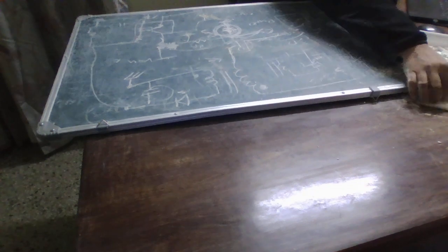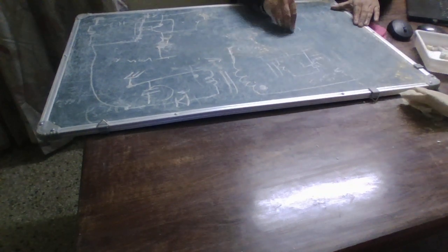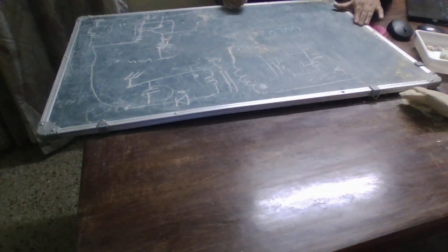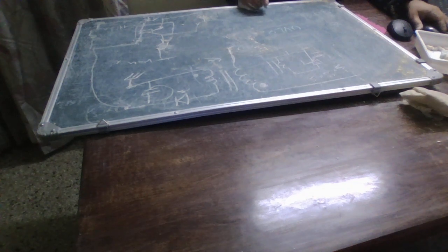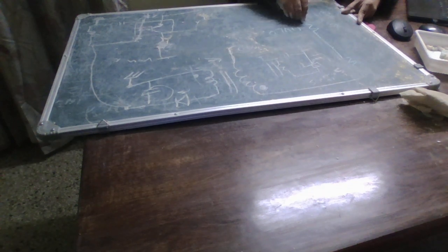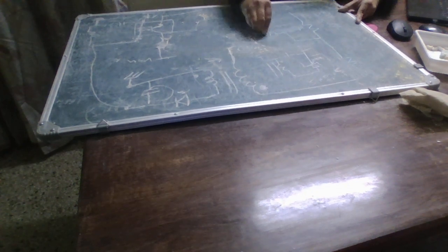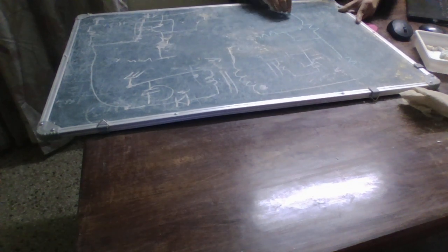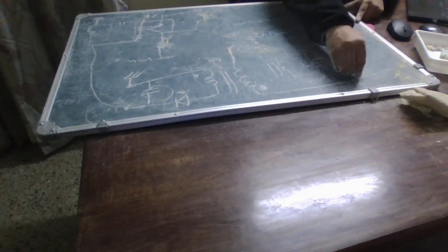Now in an IC, if you remember, I have mentioned an under voltage lockout pin, the UV pin, and again we need a resistor with that pin, because we had a voltage divider here. I am again drawing the voltage divider. This voltage is going to the under voltage UVLO pin, and this to the analog ground, and this would be ground. So we have a resistor divider. This is the input supply here.